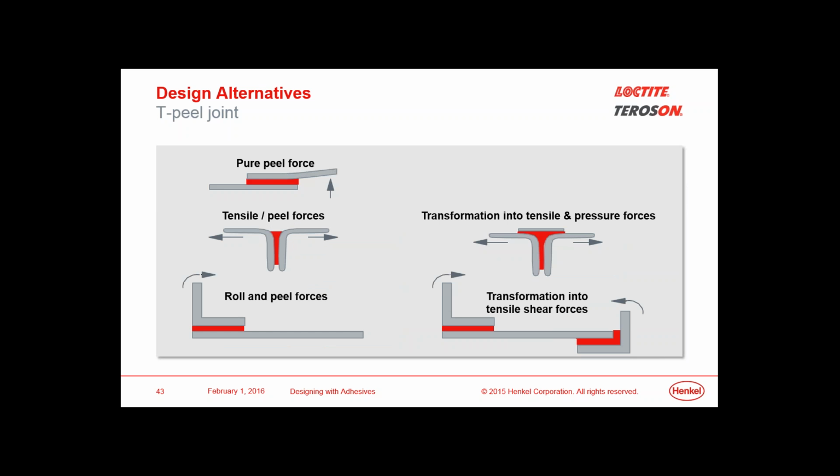These also are some alternatives to existing designs that may be subjected to a peel or a cleavage type of force. You can modify those by adding pieces to augment and to stress relieve those points that would be subject to the peel force.